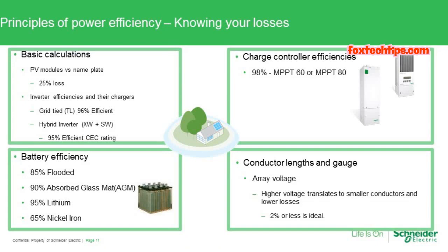So understanding your power efficiency and understanding the losses that occur within a system is really where the rubber hits the road for proper sizing. And oftentimes, if you miss one thing, then overall the system is at risk of harm, because either wire sizing isn't correct, or the amount of solar put on site isn't going to meet the needs for the customer, or the battery bank isn't large enough and doesn't meet the needs for a return on investment from the system,